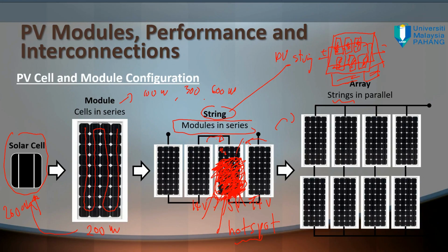Usually detection has a limitation at the string level. For one string, you check what its output is at the inverter. That's why they look at the schedule, and usually look at abnormality. If it looks okay, sometimes maybe shading or sometimes maybe there's a spot. But if there's not much difference between strings, then no problem. Like that. Okay, done. Everything is at the inverter, you look at the inverter output. That's the easiest way to trace, I think.